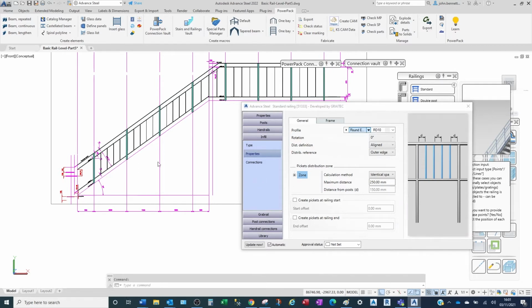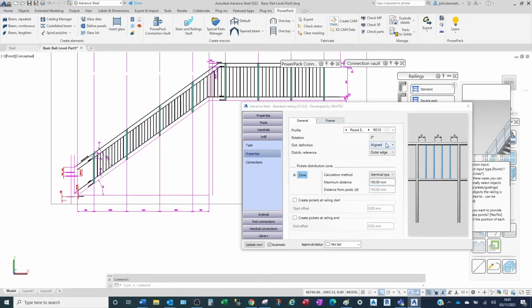Then we need to start looking at the arrangement for this. You do have a tree structure in here, but it's normally to do with straight or curved rails. And here I will not change this. I'll leave this to our formula that we use to work out the rails. I just need to change the spacing in here. So this will give an identical gap between each one. And again, I'm probably going to just change this to be straight. That means this center will now be 100 millimeters in the horizontal direction for every single infill bar. So when that's done, that's the basis of that rail.